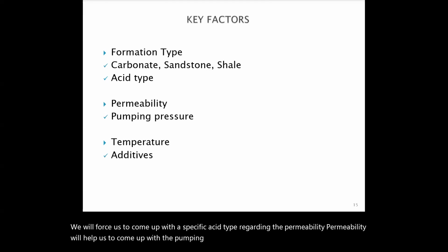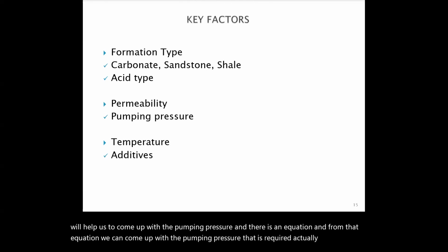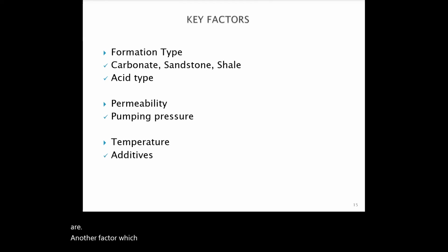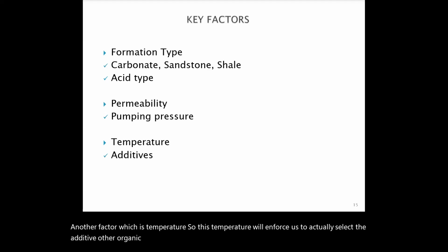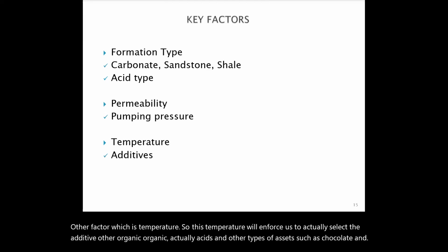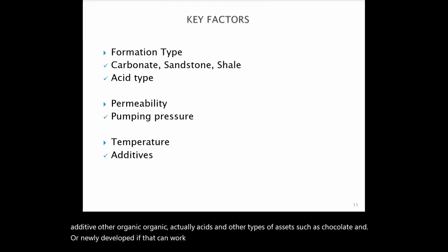There is an equation, and from that equation, we can come up with the required pumping pressure. And there is another factor, which is temperature. The temperature will force us to select the additives, other organic acids, and other types of acids such as chelates and newly developed acids that can work for high temperature wells.